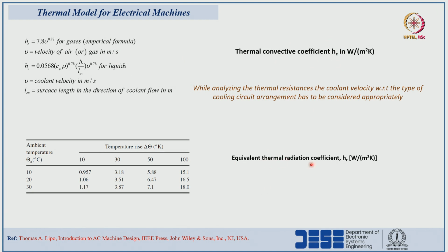Similarly, the thermal radiation coefficient we can consider from this table, with respect to the different ambient temperatures and different temperature rise. In watt per meter square Kelvin, we can select it from this table.